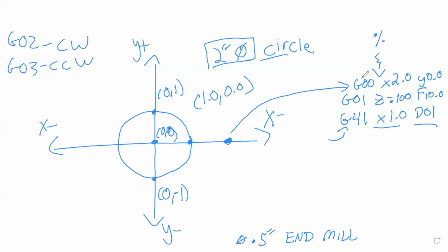So now our new cutting location will be right here. Okay, because we have cutter compensation on, we're going to be traveling left of the workpiece, and we need to put our next line of code in. So let's erase some of this.